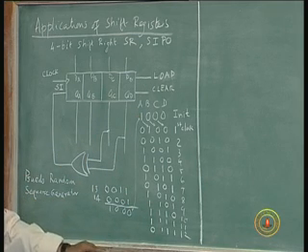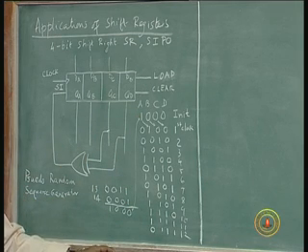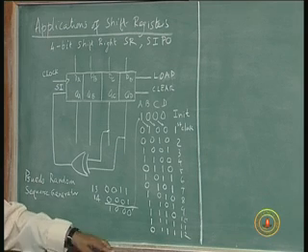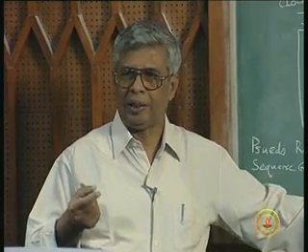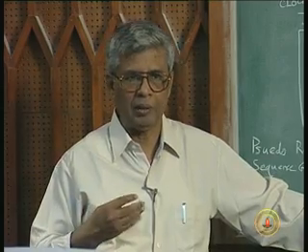If the initial pattern is different, then we will have a different sequence, again 15. So, it is not completely random, you know that after 15 it will be repeated. So, that way it is pseudo random. Pseudo random means semi random, it is not completely random. You know there are 15 patterns going to come, and if you know the initial pattern you can guess the other patterns. So, that is why it is called pseudo random.